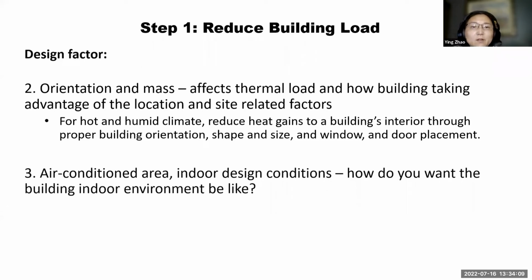Another design factor is the air-conditioned area and indoor design conditions. That determines how you would condition the space, or whether you want it to be naturally conditioned or naturally ventilated. What temperature would you like to design the indoor condition to? Is that higher or lower? If it's set higher, it will probably reduce your cooling energy use a little bit, or even more. If it's set lower, it will probably use more energy.